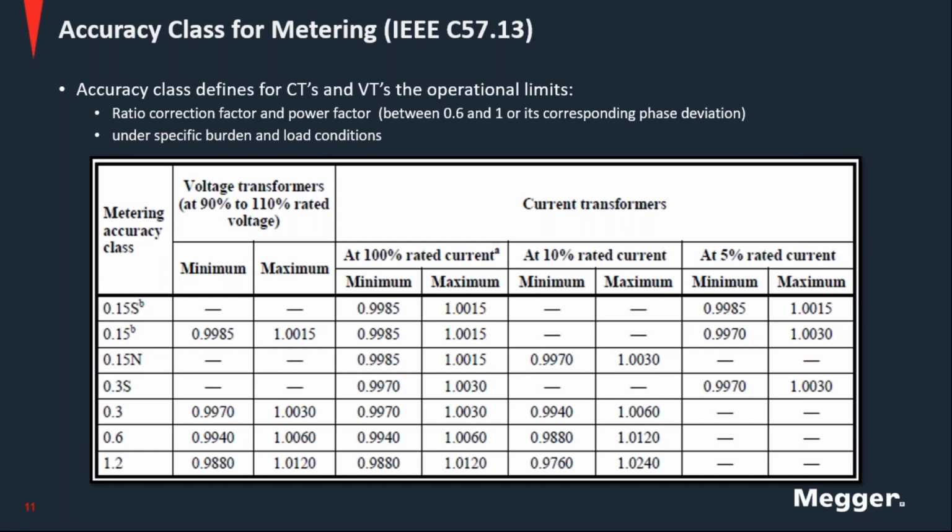So you have relays, you have coils, you have meters connected to these transformers, and well, it is providing signals, voltage or current, but of course it needs to provide some power to these elements. So the loading conditions must not exceed certain limits. So right now we're focusing on the burden, sorry, on the accuracy class, and later on we'll talk about burden.